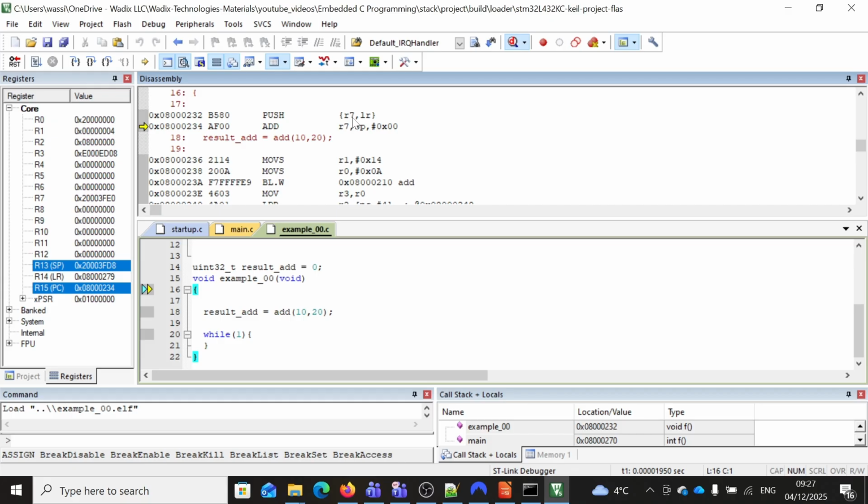In our case, the different registers within an ARM Cortex-M are 32-bit registers. If we push 2 registers into the stack, then the stack pointer will decrement by 8 bytes.